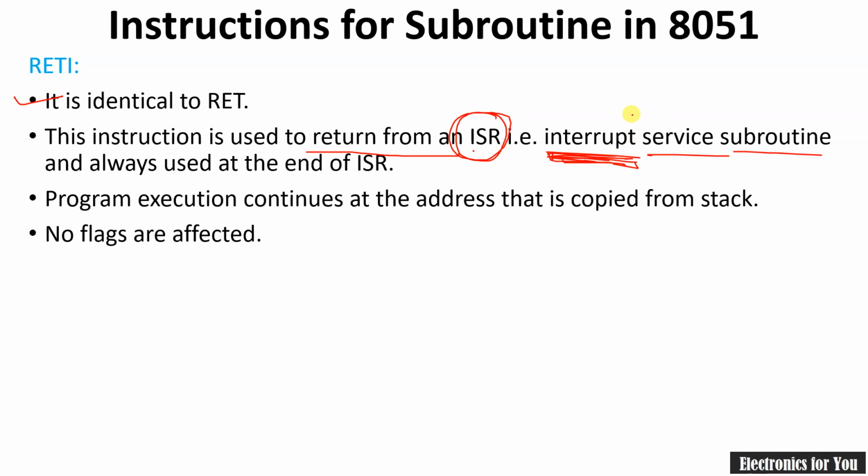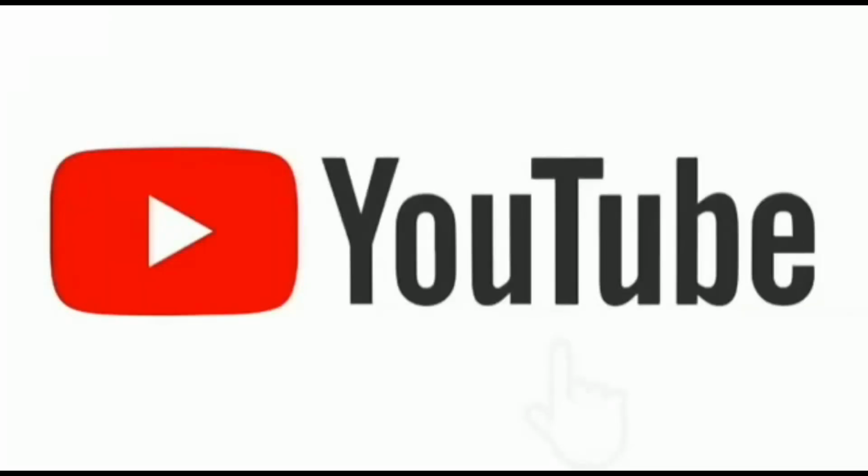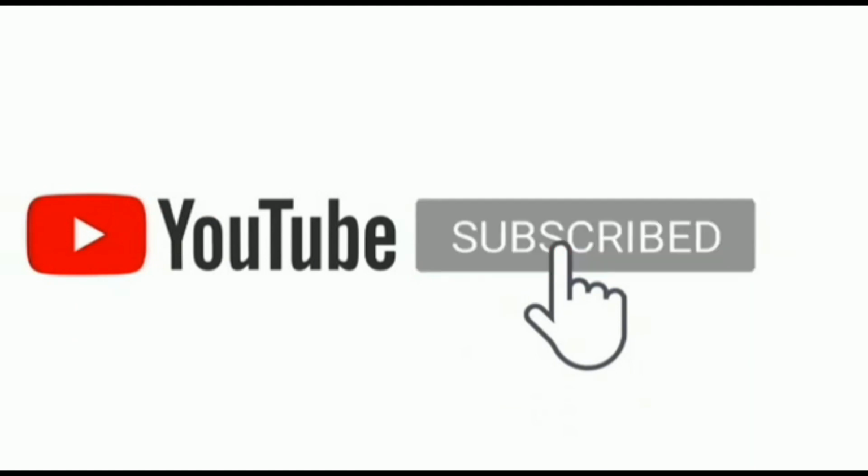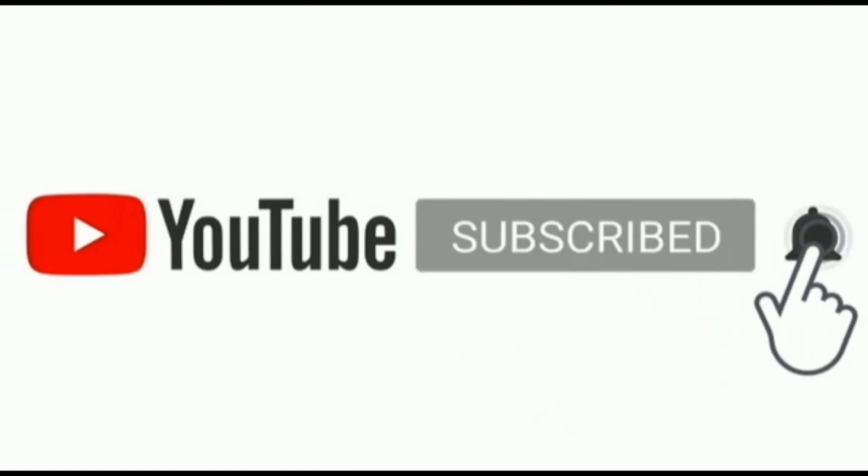Once an interrupt signal is there, we will use the RETI instruction. Further, the process for RETI is the same as that of the return instruction, everything will be just the same. Program execution continues at the address that is copied from the stack. No flags are affected. Okay, everything else will remain as it is, only it is used for the interrupt service subroutine.